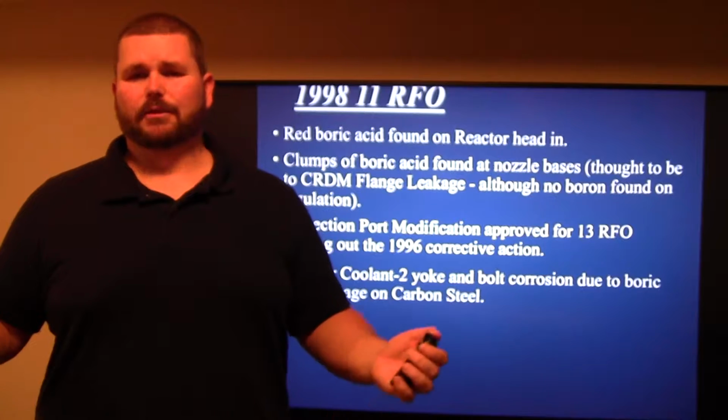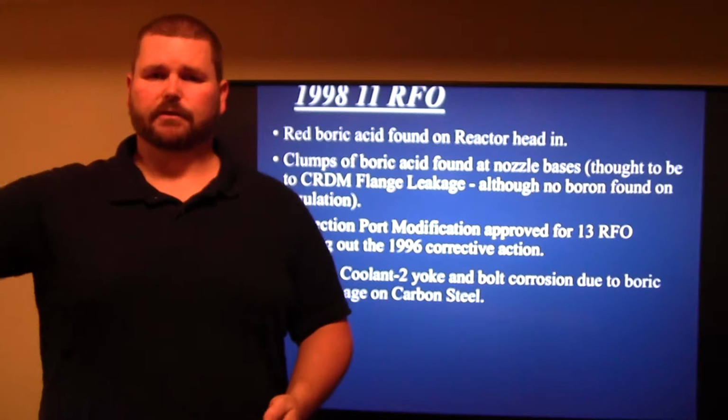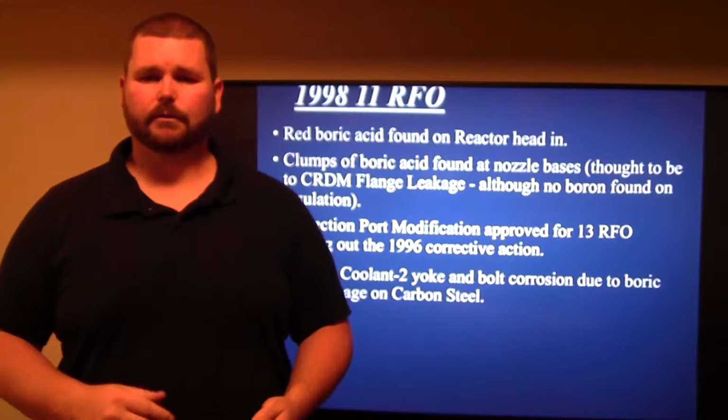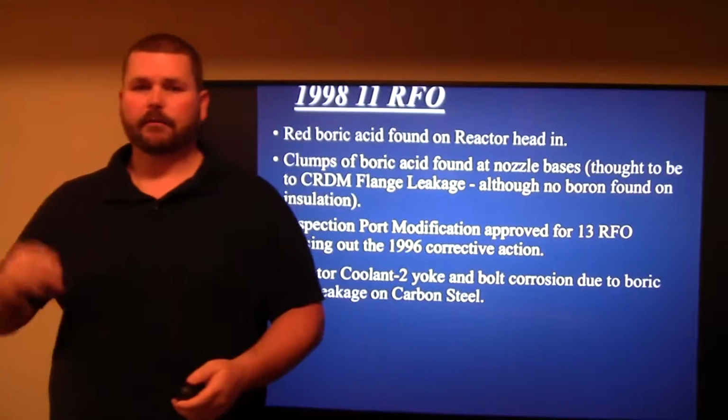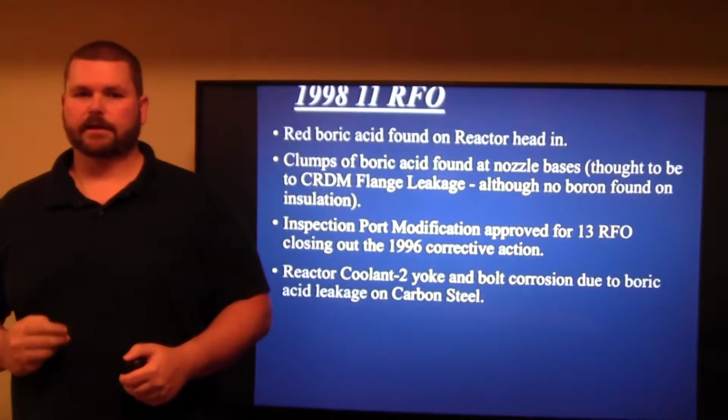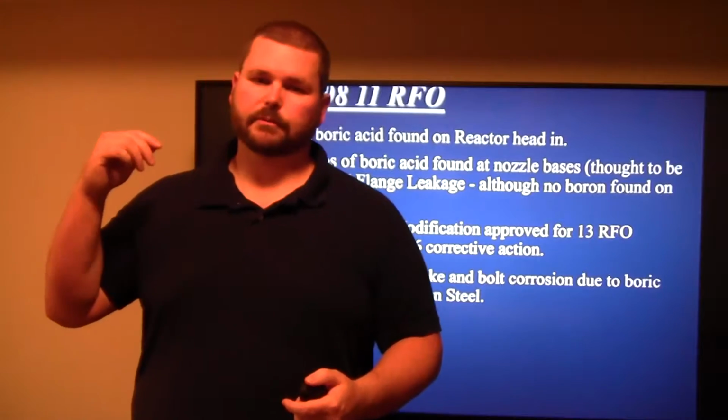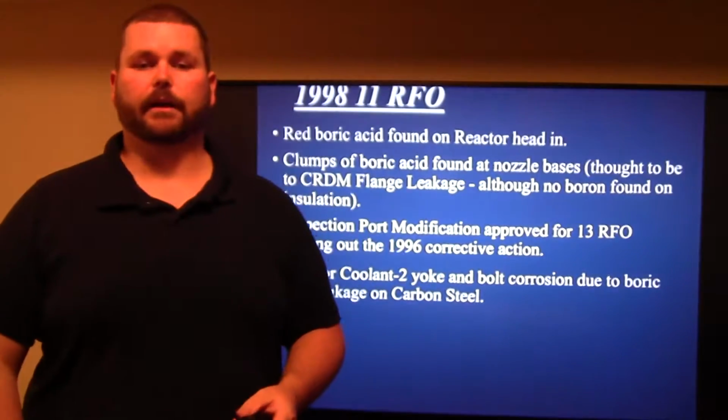And they said, okay, well maybe we do need that inspection window, but let's push it off to the 13th refueling. We can't do it in the 12th. Let's do it on the 13th. And now we have a third incident with boric acid corrosion on carbon steel where the reactor coolant pump 2 yoke and bolt corroded due to boric acid.